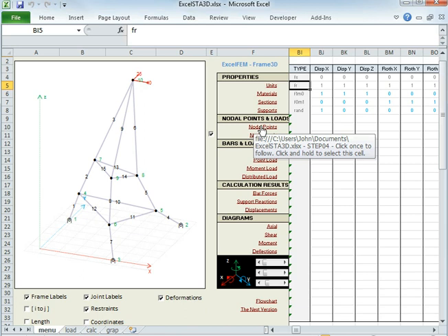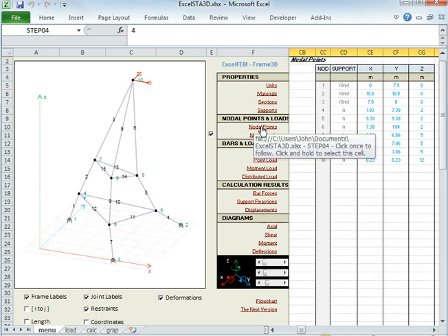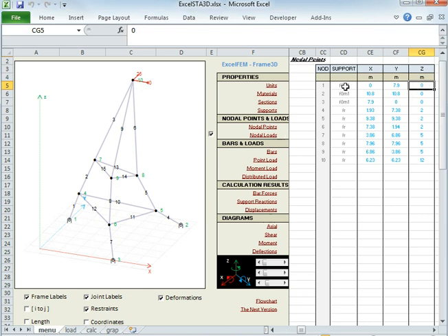The next thing we're going to look at is nodal points. Nodal points, very easy to understand. X, Y, Z position defined here, and the supports are defined here. So the support at the bottom, where we have a pin connection, is taking, again, reading from the support section. We can select different supports as we like, and the supports between normal beam-to-beam connections are this, like joint number 5 here, which is there, is free to move in any direction, only constrained by its connection to the